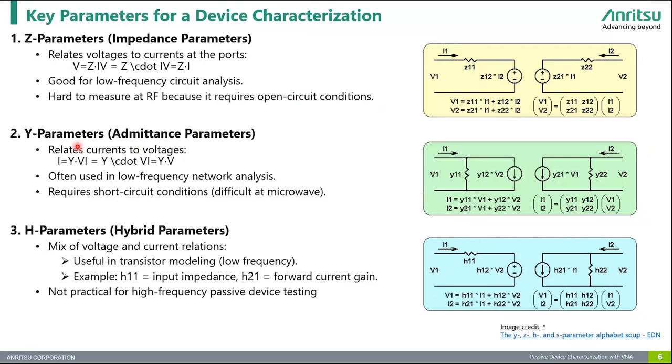If you come to the Y parameters or admittance parameters, which relate currents to voltages, these are the dual of Z parameters and are also used in low frequency analysis. However, they require short circuit conditions, which again are impractical at microwave frequencies.